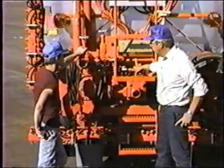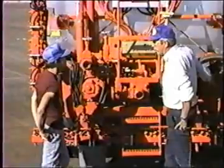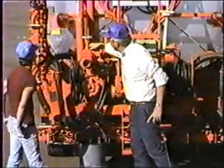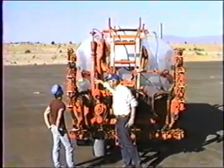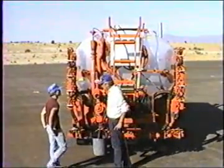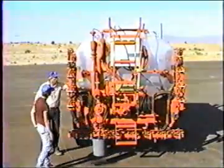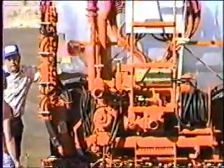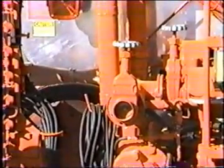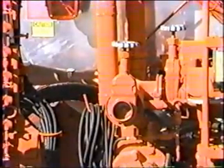Okay, the diesel's going in, and it's going the circulation path of the spray bar. It's going to go the entire route. Okay, it's going to come back around, and finally, remember, on the circulation path, we're coming up this line to the relief valve. Okay, on the back side of that line, there's another ball valve. Another 3/4 inch ball valve. It's got a yellow handle on it. Any of these ball valves, when the handle is perpendicular or crossways with the pipe itself, that means it's closed. When we line that handle up with the pipe, it's open.